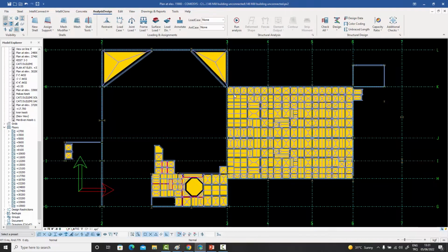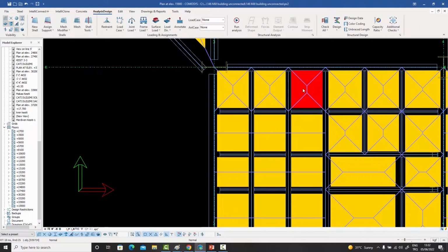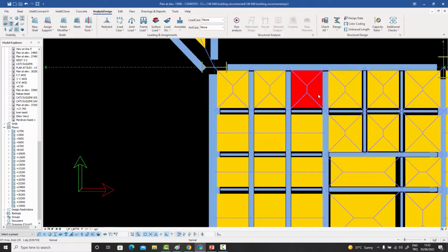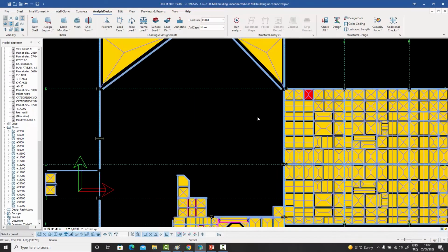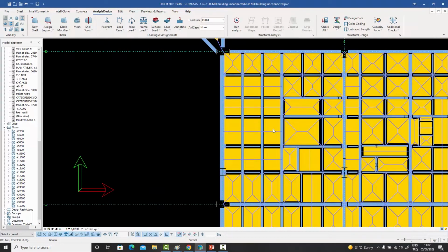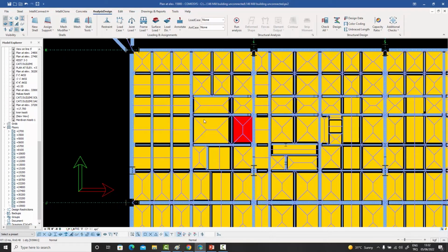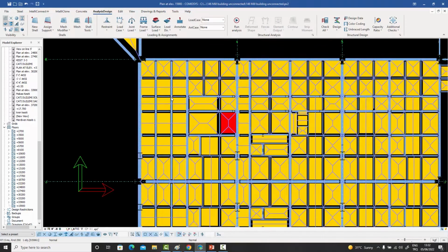It basically goes and finds all the possible combinations where loads could be transferred in this building. So let me turn on the beams like that so you can see it more easily. It finds every possible area where you could have a load transfer. And for that possible area, depending on how the releases of the elements are, it also suggests a load transfer direction, which you can then modify later.